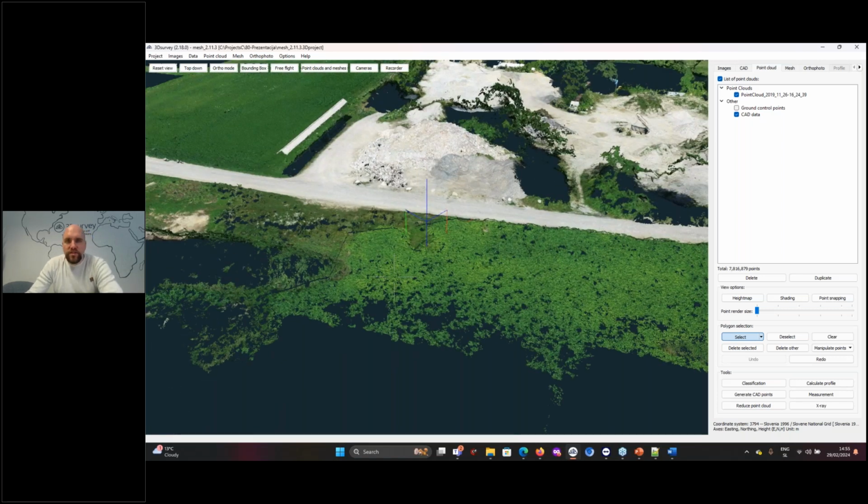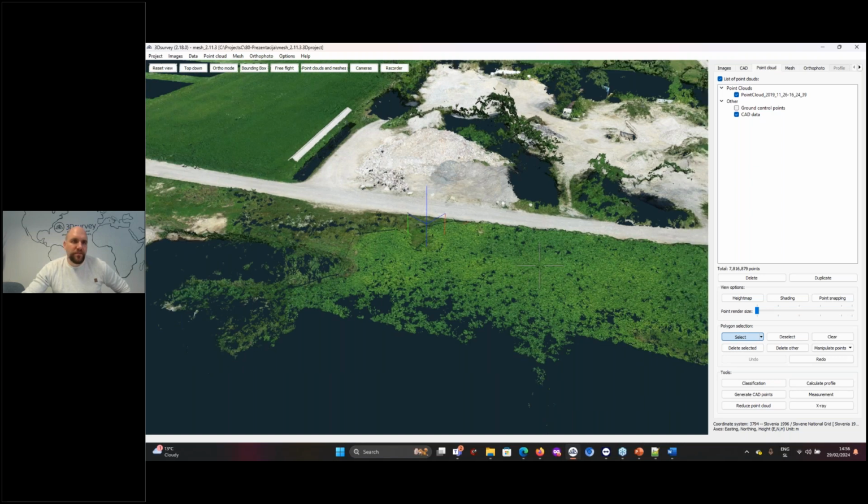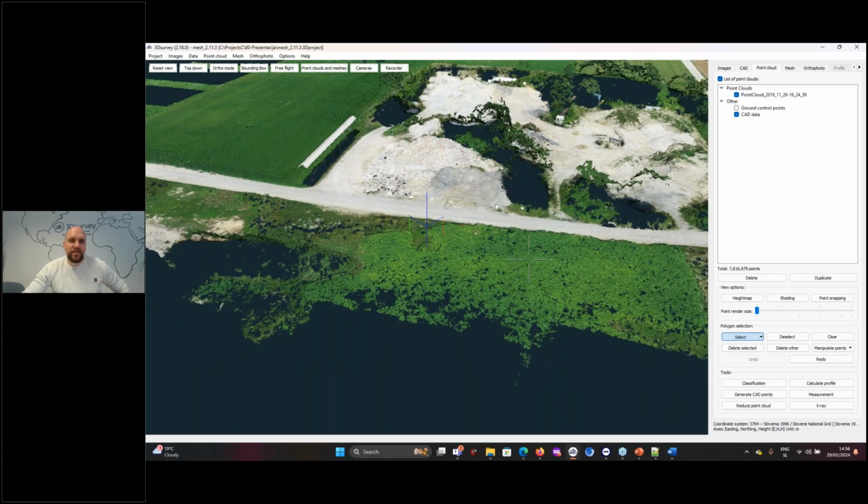The second thing is water. So if we have a big body of water and we do a mapping there, sometimes we will see a little bit of the ground through the water, but the ground there is not accurate because the light, of course, breaks where the air and water meet. So underwater photogrammetry only works as underwater photogrammetry. You need to have camera underwater as well. Okay, so that was the question that we had.